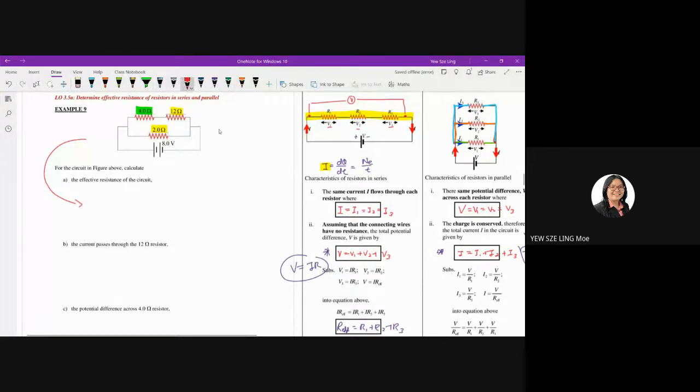And before I simplify it, I'm going to give them names, R1, R2, and R3. How am I going to simplify it? Let's identify the junctions for this resistor. If you look at this 4 ohm resistor R1, the junctions that are closer to it are these 2 points.